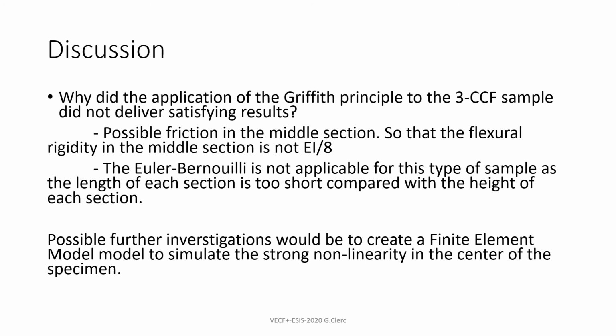So probably we have a big mistake because the Euler-Bernoulli equation doesn't consider shear deformation. One option which should be investigated in the future is to use a finite element model which could simulate first the shear deformation and secondly also the friction in the middle section.